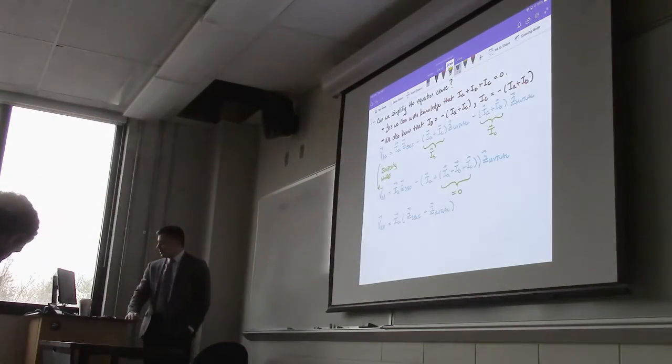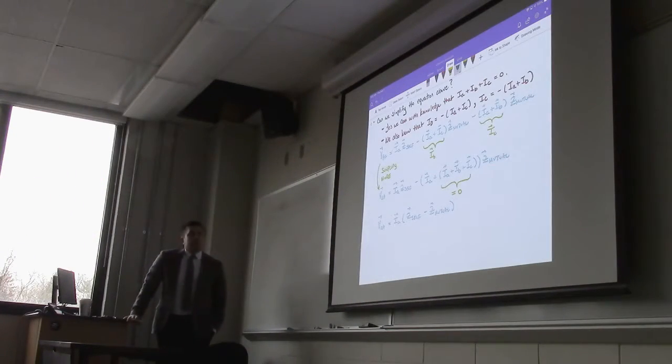And so now you can see why we use the minus for the Z mutual in the very beginning. We could have used the plus, but it just would have flipped the value, the coefficient. And so that's how we can represent both the self and the mutual inductance on phase A or any of the phases without referencing the currents on the other phases, right?